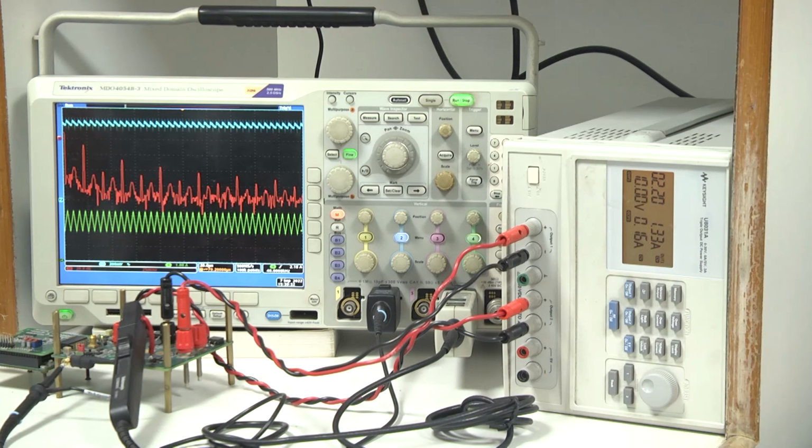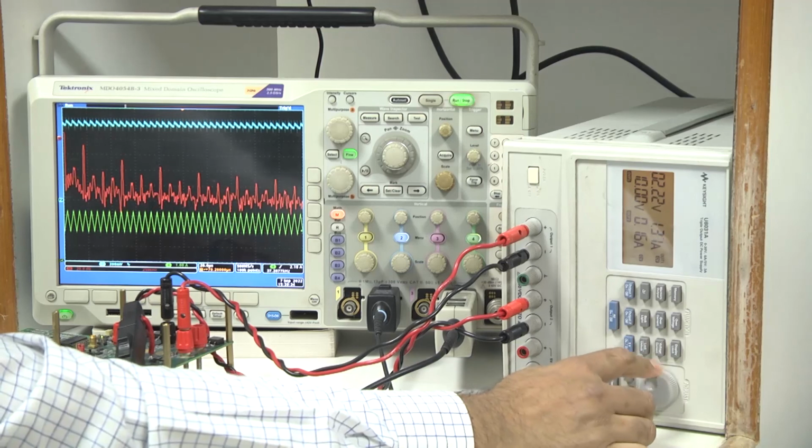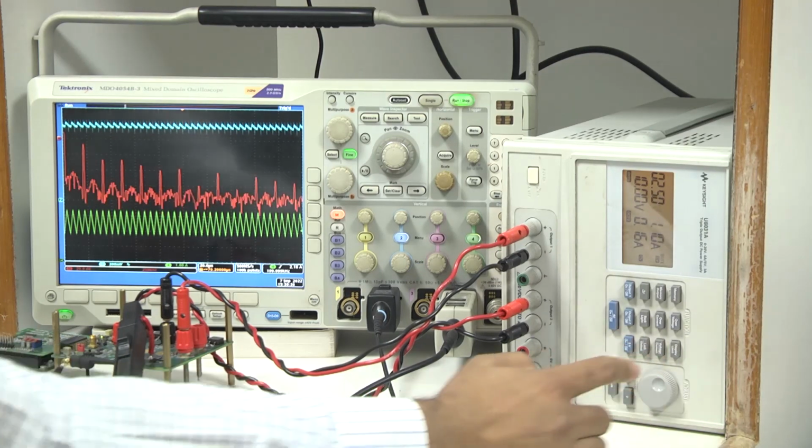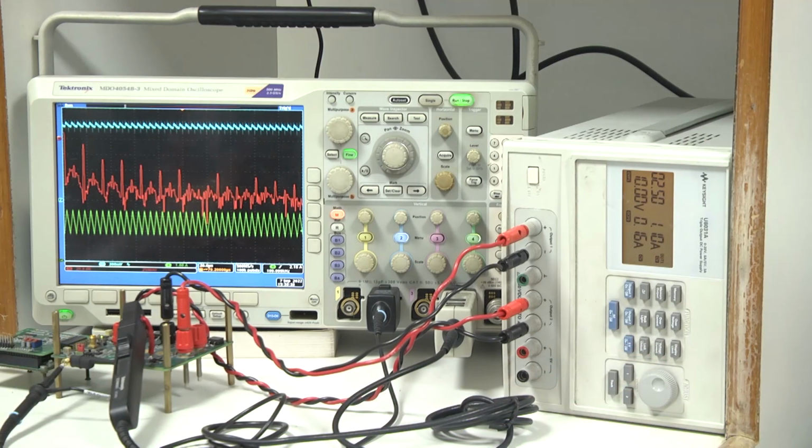With the ramp it is stable, and if we further increase to 2.5, it was stable in both cases. In this way we have seen that the ramp compensation can make it stable. When there was no ramp compensation, it was unstable below 2.25, but when we added the ramp it was stable, though not stable even at lower voltage. So we need to increase the ramp, and we have discussed that a higher ramp can take the current mode control close to the voltage mode control, which is not desirable.